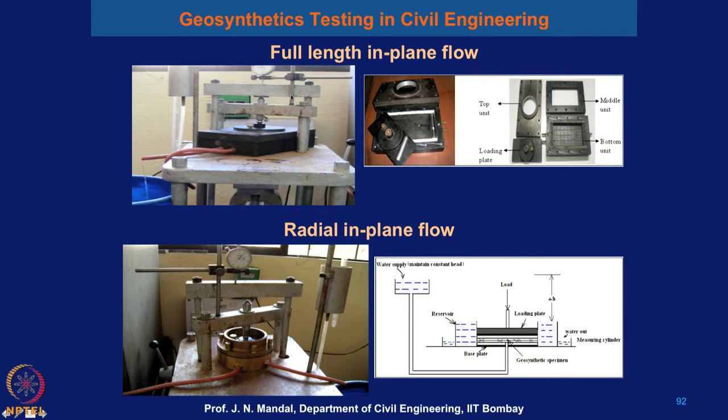and here the size of the sample will be 200 by 100 millimeter, which is located in between the two plates, and then you are applying the load, and then you are measuring the head. So, this is the kind of equipment we use for the determination of the full length in-plane flow.